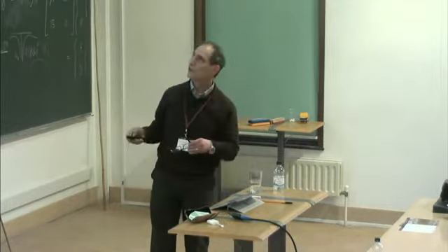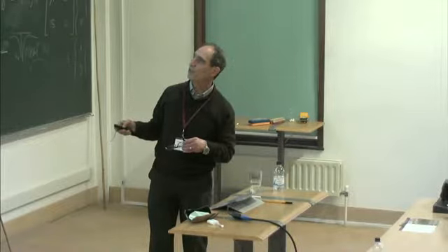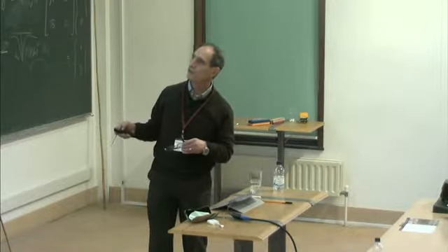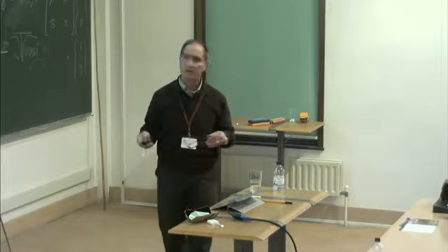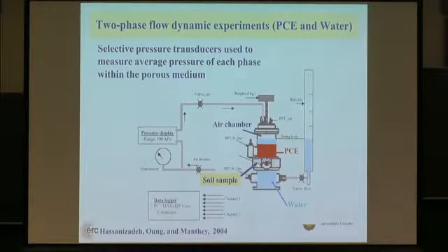That's why it occurs. So, as I said, how about if you make these measurements not statically, but fast, dynamically? So we have this setup where the soil is here, and then this is sand. And we have an oily liquid here. This is the non-wetting phase. Water is here. And then we put two pressure transducers here. One of them is hydrophilic, the other hydrophobic. So one of them measures the pressure of the red phase, the other measures the pressure of the blue phase.